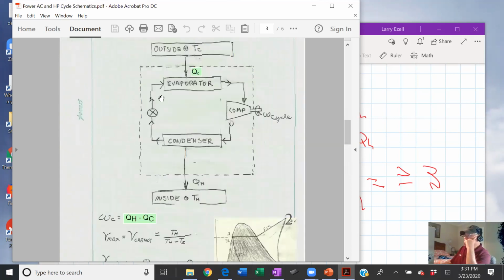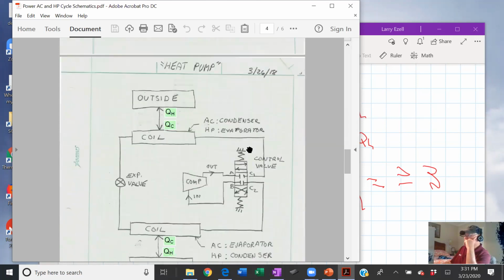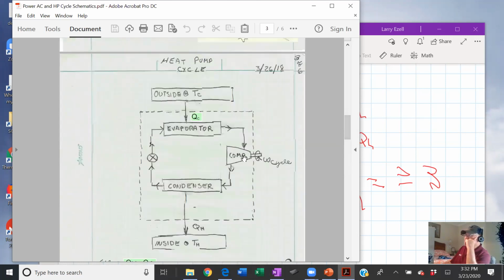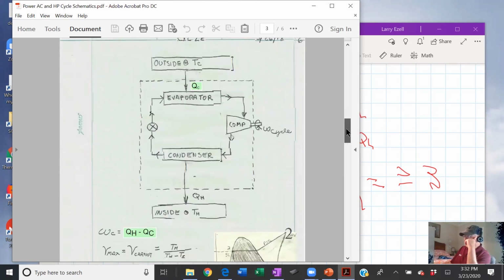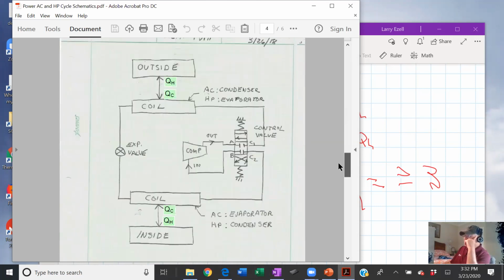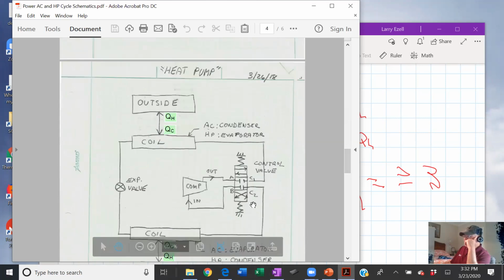How do they actually reverse this flow in the real world? All right. They do it with a switching valve. And I know you don't know hydraulic schematics, but this is a schematic of a switch. You don't turn the compressor one way for an air conditioner and another way for a heat pump. You do that, you're just going to end up with a basket full of failed parts. So what you do, these systems have a reversing valve under control of the control system. This shows both ports blocked. Well, you wouldn't have it in this.